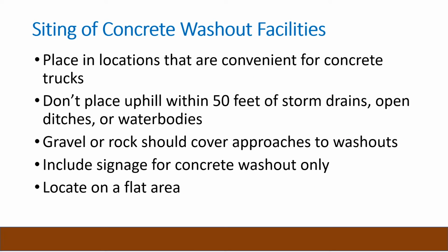Place concrete washouts at locations convenient for concrete trucks. Most are labeled. Don't place uphill within 50 feet of storm drains, ditches, or water bodies. Prevent track out by using rock over approaches to the washouts. Use signage and locate on a flat area.